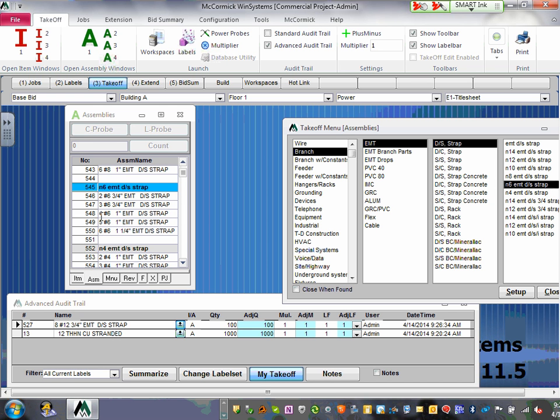So now here, if I have a feeder, if I have a branch circuit, guys, 4 conductors, number 6, with half an inch EMT conduit, it's already there. So, Karen, make your life easier. Your feeder, try to match your feeders with what we have, guys. So if you have a conductor similar, close to number 8 or number 6, use number 8 or number 6 and pull it as that conductor.